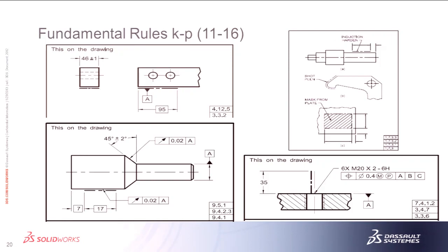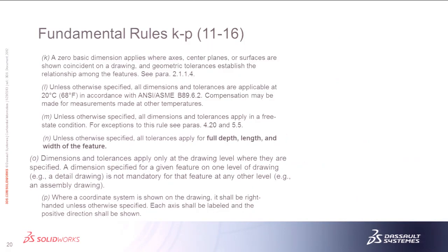So would you use multiple chain lines if you still have a tolerance, it's just not as tight? When you don't specify here, that would probably go to the block tolerances at that point in time. Or if you put an overall dimension on something and control one with a GD&T, it's going to go back to. So I guess your hierarchy there is going to be GD&T, then your standard coordinate tolerancing, then your block tolerancing. So yes, they're still toleranced, but it's going back to block probably at that point in time.